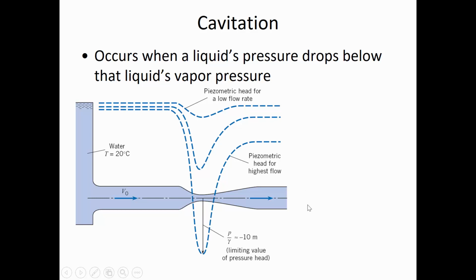Let's maybe put a valve downstream, so we're controlling the flow. Now we're going to allow the water to move a little bit faster through this pipe. So the velocity is a bit faster. That means the pressure is going to drop lower, because the bigger the difference in velocity between point 1 and point 2, the bigger the change in velocity, the bigger the change in pressure.